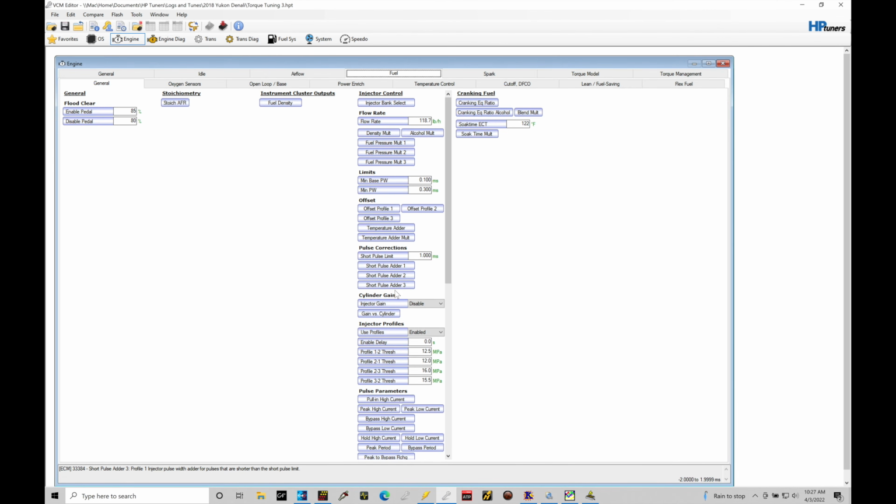If we start to spray the secondary fuel, we're going to get in a situation where we have too much fuel coming into the engine. Well, we have no way to properly characterize this. We have no table in the programming language here that can allow us to say, okay, secondary injection spraying with a secondary injection controller. This would be an aftermarket subcontroller.